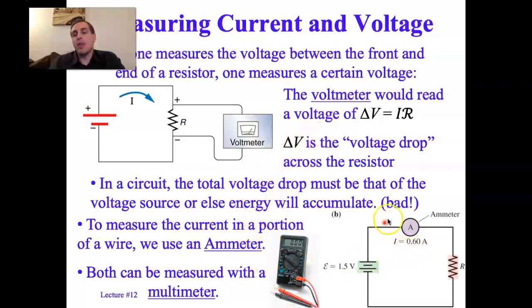By the way, it is possible to fry an ammeter because, again, the current goes through the device itself. I'd recommend that most of these multimeters, be they expensive, are only rated for 5 to 15 or maybe 20 amperes. So do a back of the envelope calculation and then make sure you put the setting on 5 amperes, sort of like the maximum current available for the multimeter before you even have any charge go through this device.